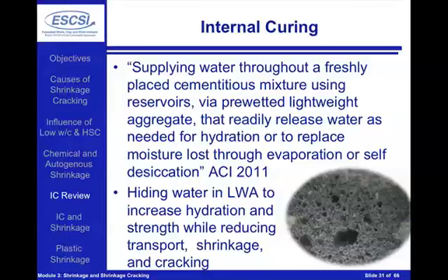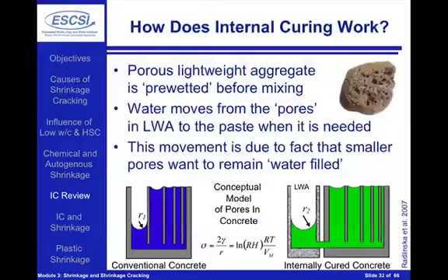It's going to increase the hydration of the cement, of the supplementary cementitious materials. By doing that, it's going to increase the strength of our concrete. It's going to reduce the transport properties of our concrete. And what we're specifically talking about in this module is it's going to reduce the shrinkage and reduce the shrinkage-induced cracking that occurs inside of these materials. So the whole idea here is to use pre-wetted lightweight aggregate that will supply water at the right time to fill in the vapor-filled space that's caused by chemical shrinkage. And by doing this, we're going to improve hydration, we're going to reduce shrinkage, and we're going to cure our concrete from the inside out.